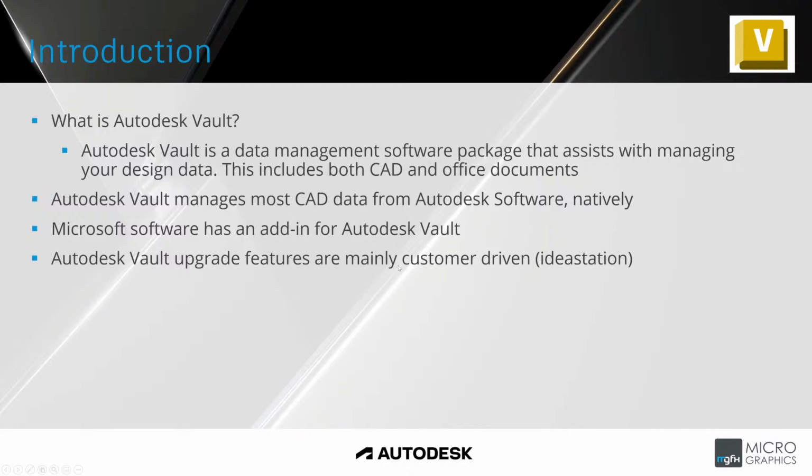Okay, so moving along, what is Vault? If you have never looked at or seen Vault before, Vault is basically the data management software package that you get with AutoCAD, the full AutoCAD, not AutoCAD LT unfortunately, although Vault Pro does link into your AutoCAD LT. Its main function is to work with Inventor. As you know, with Inventor, everything doesn't work in one part or one file. It's all spread over. You've got your assembly files, your part files, your drawing files, presentation files, sheet metal files, weldment files. Now, how does that all get managed?